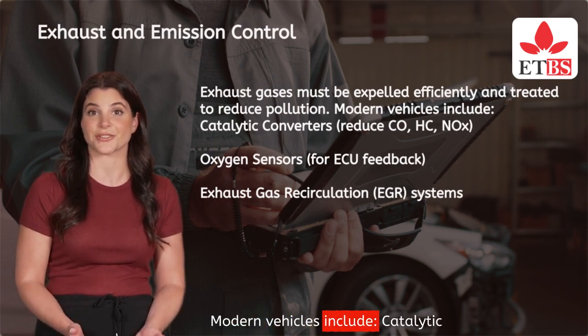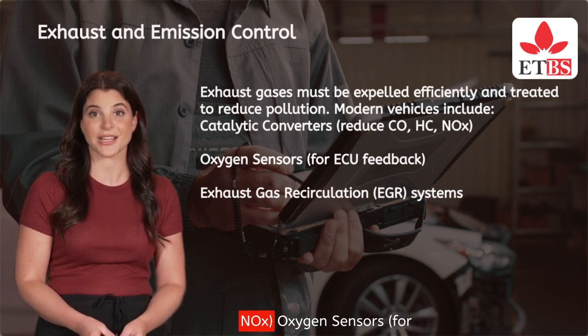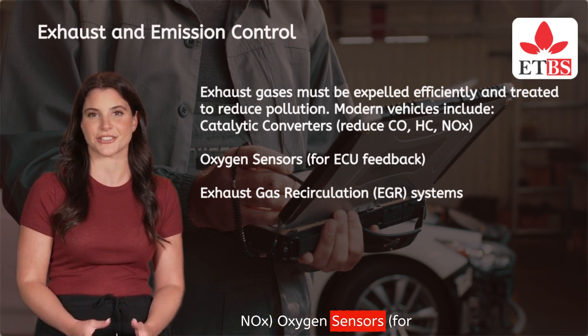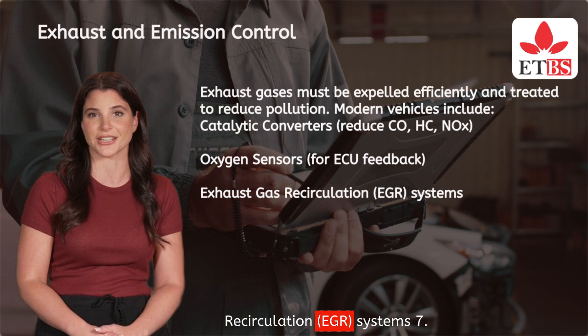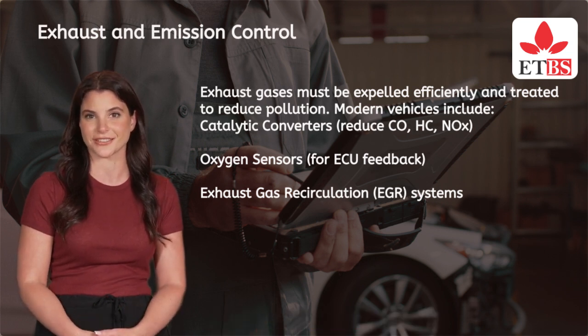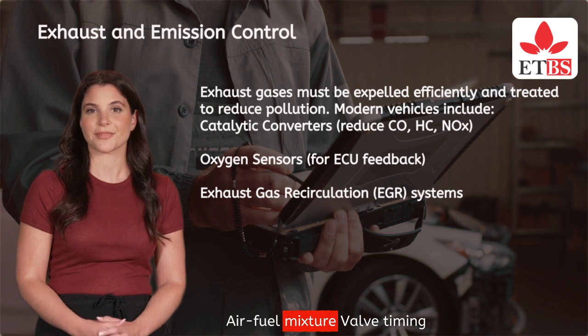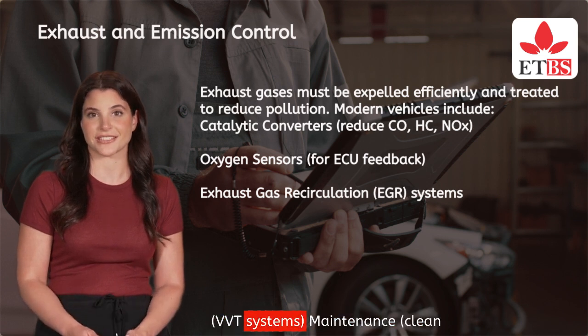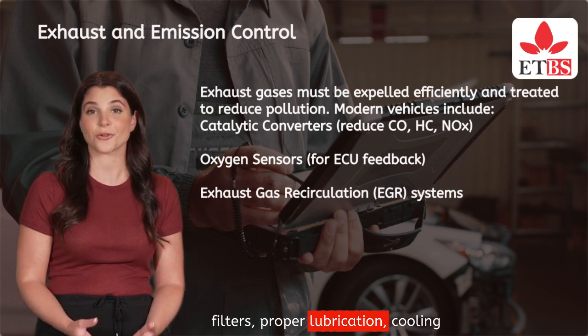Modern vehicles include catalytic converters reduce CO, HC, NOx. Oxygen sensors for ECU feedback. Exhaust gas recirculation, EGR, systems. 7. Engine performance and efficiency. Several factors affect efficiency: compression ratio, ignition timing, air-fuel mixture, valve timing, VVT systems, maintenance, clean filters, proper lubrication, cooling efficiency.